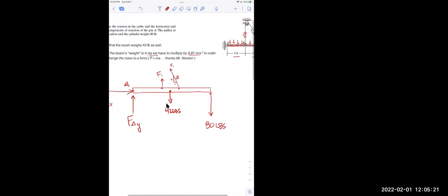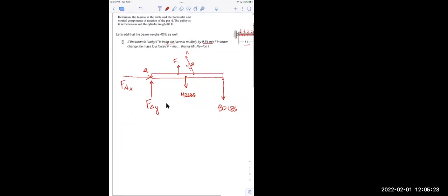So the hard part of a free body diagram is you can't miss any of the arrows, because you're going to be adding all of these forces and setting them equal to 0. You're going to add all the moments and set them equal to 0. Notice the beam doesn't know what supports it's connected to. It just feels forces pulling on it. And again, I made assumptions about what direction those are going. I actually don't really know for sure if I have that right.